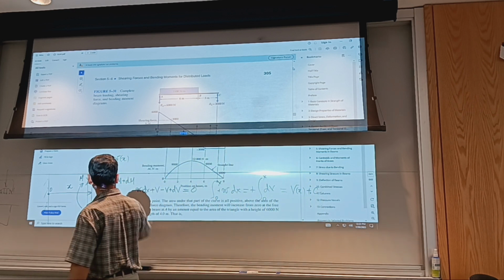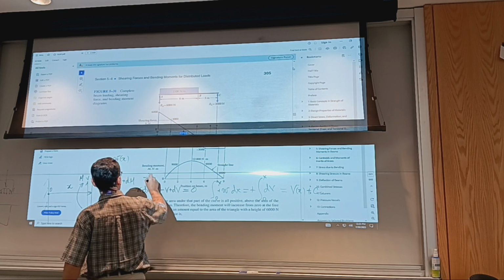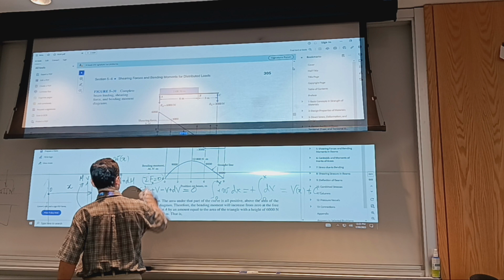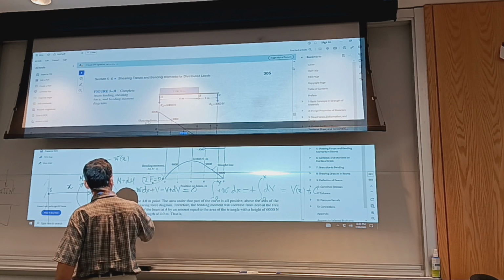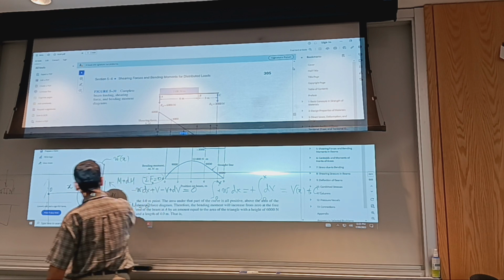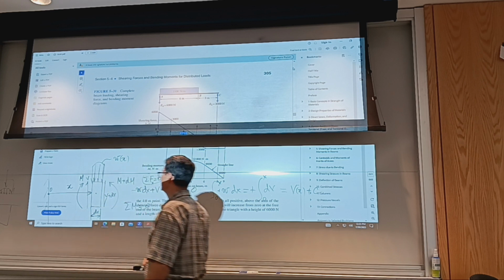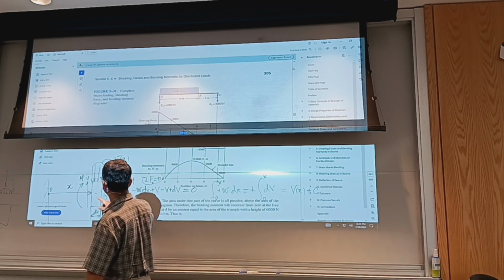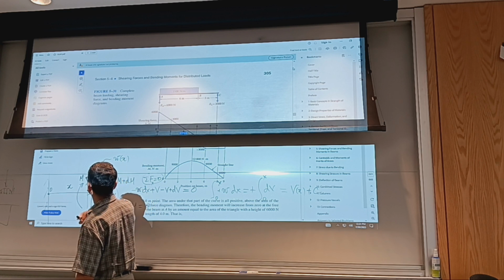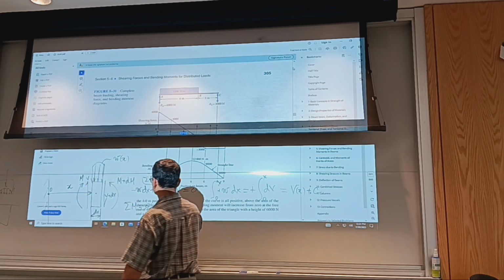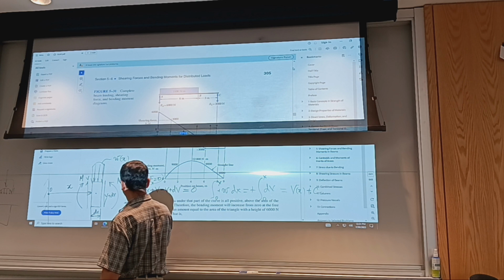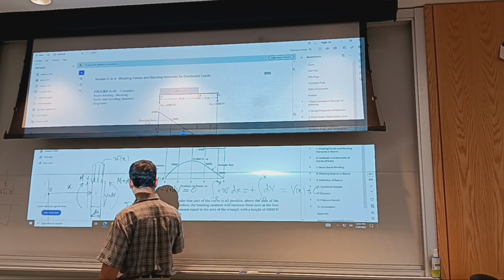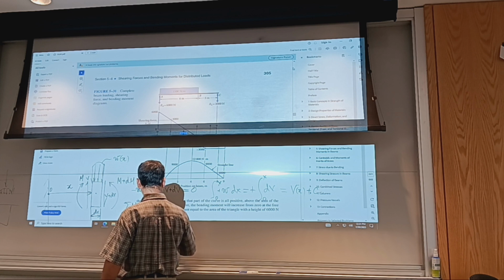And I can write moment equilibrium. So this was for the sum of forces equals 0 in the x direction, and then I can sum moments about the center of the element, assuming positive counterclockwise. So we're going to say negative M, this is 1, plus M plus dM.